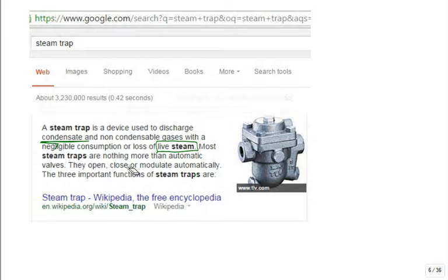There's CO2, there's oxygen, a whole pile. Well, they like to come out when it's warm water, steam. So they'll come out where it's low pressure, high temperature. Now you have gases separated from the liquids. Sometimes they'll go back into solution. Sometimes you just get them out of the system. So you'll have non-condensables, and the engineers have to design it to get rid of them.